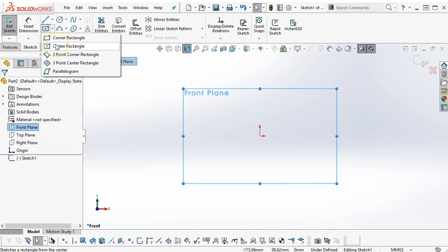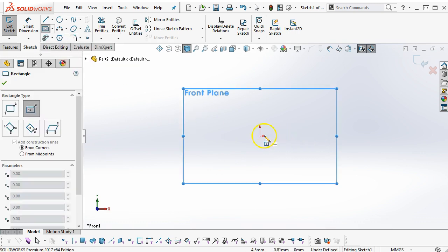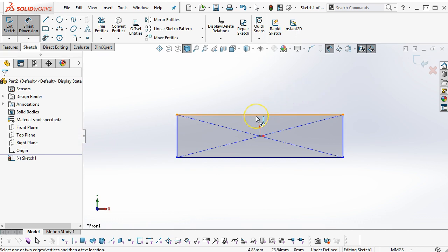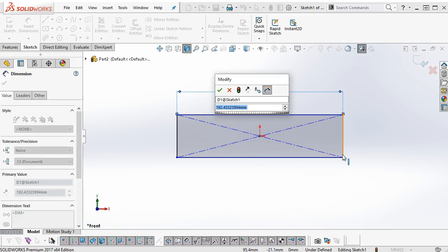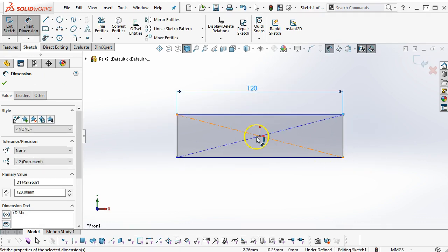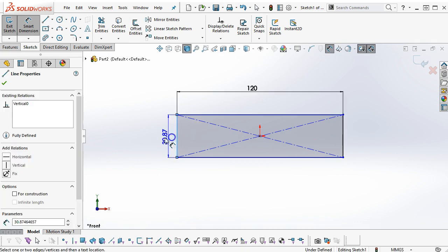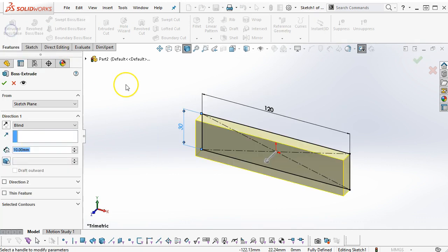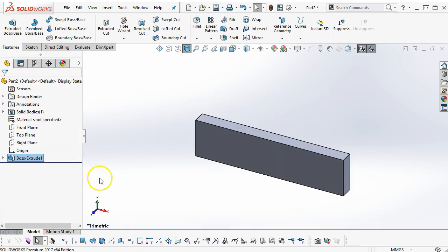Open up the sketch, and then we can use a corner rectangle, which is probably good enough, but if we came off of that corner and out this way, or I'm making the choice with my center rectangle to center the geometry about the origin. All right, so keep in mind that you have those other options available, that not everything just gets related to the corner and you're kind of stuck with it. Wherever makes sense and whatever you can visualize in the geometry. So 10 millimeters.